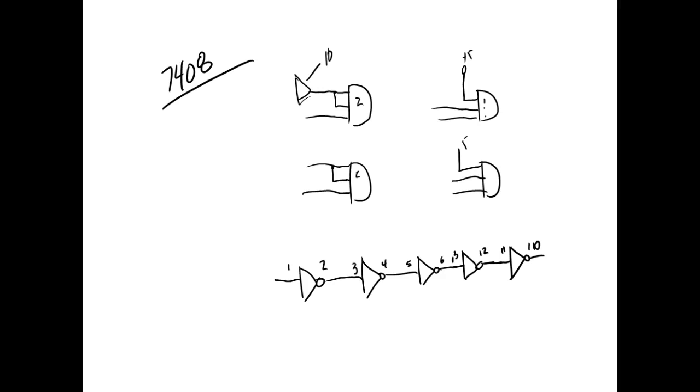You understand? So if this thing takes 10 nanoseconds to fall or less, then we're talking about a real high rate that this scope just can't watch, just can't read. And it's going to have a hard time with this, but take my word for it, it is pulsing all the way to ground or to 0 volts. It's just that it's already on its way up before the scope can get it down there.